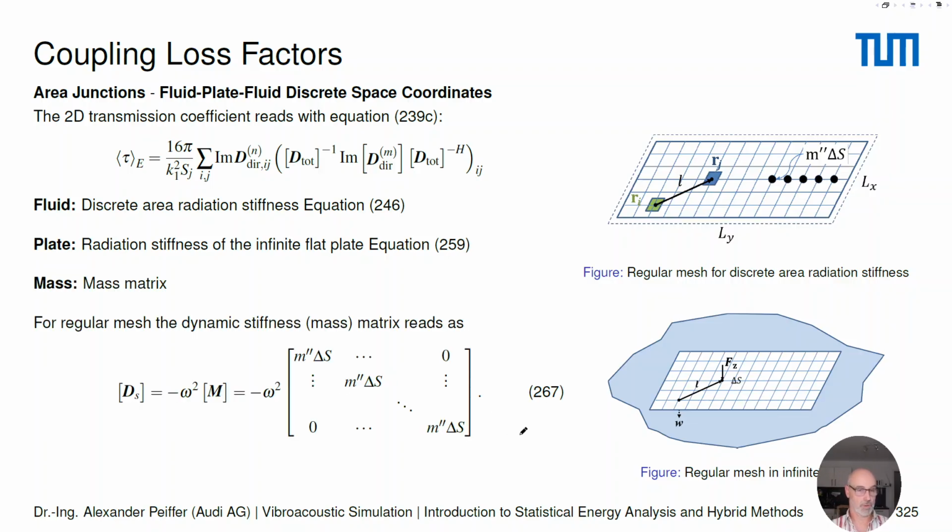So we no longer have any, let's say, mass formulation. But what we can also do, and that's a super simple thing, is say, okay, I take a plate which has no stiffness at all. There's only mass. That means my stiffness is just given by a mass matrix. I just take the mass per area multiplied by the surface area of my element here. This gives us a very simple expression. This would be, let's say, the perfect expression of an infinite mass distribution.